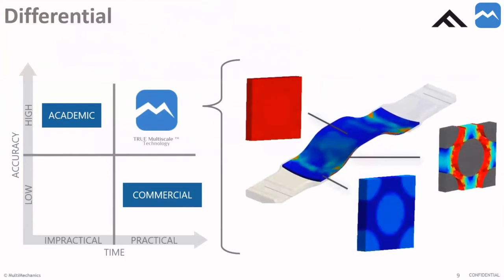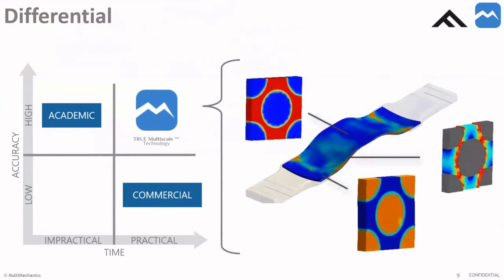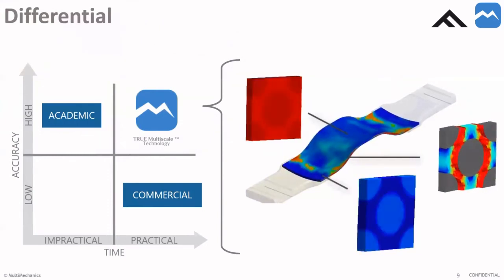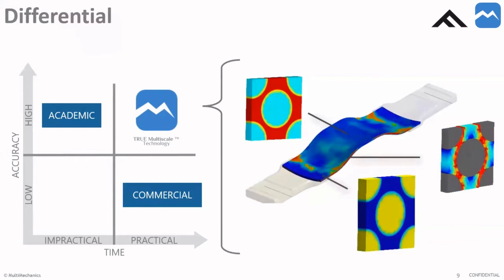On that third RVE on the right, we can see some damage trying to develop within the resin in between the fibers. You start to see how damage begins to evolve, and how if you develop failure in certain areas, the stresses begin to migrate to other RVEs, load those appropriately, and then they fail. So it's how you show progressive failure within a part, which gives us our high accuracy.